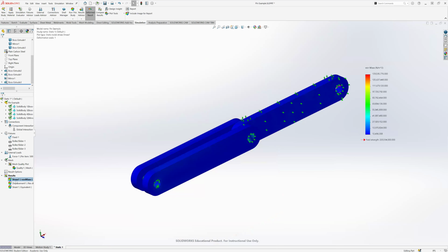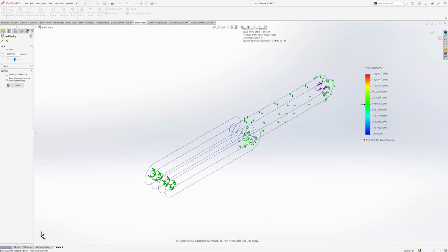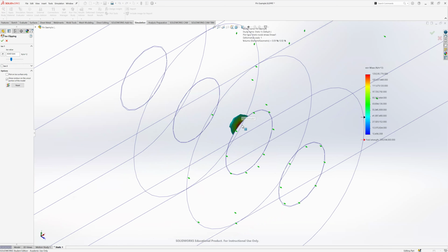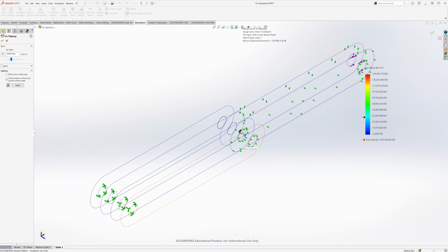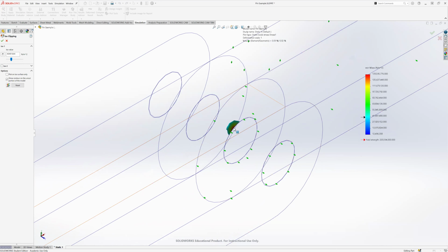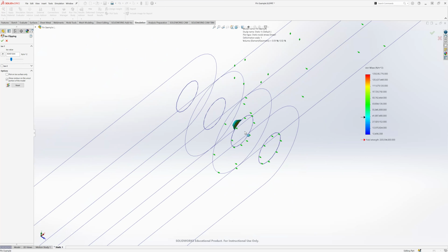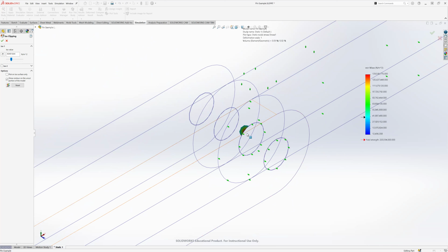That's a great one. The other one that's also really nice is an ISO clipping. So what this will do is I can actually adjust the stress level in this case. Again, I can also do this for displacement. I can lower it or heighten it, and it'll put the areas where that stress or above has occurred. So we can see above this, it's really only a very small area. So in a thing like this we could probably consider it a stress concentration.